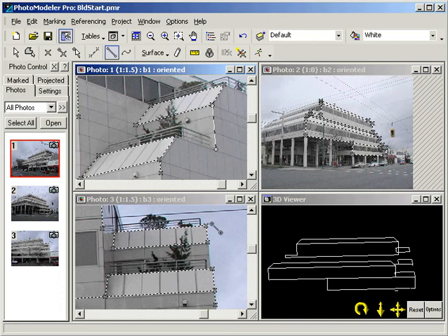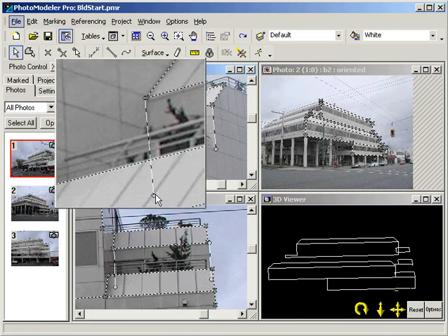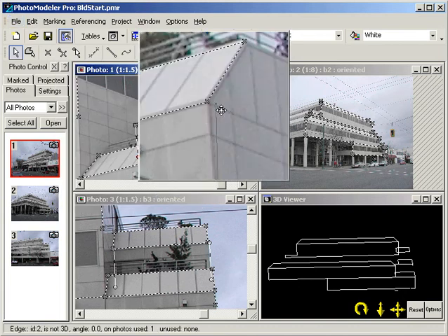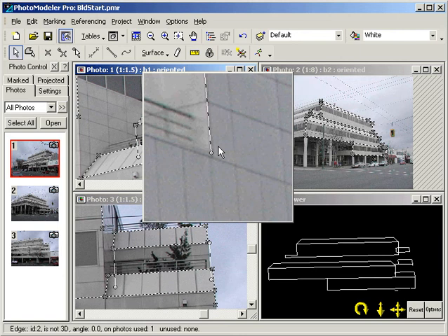We mark the rest of the edges in the patio area of both photos. Again, we can't see the endpoints, so we estimate its end position. The edge's endpoints do not snap to regular 3D points. The position of the edge endpoints must be moved close to the corner so the model will look correct. We mark this point so it closely matches the corner marked by the regular point. We use Alt-Zoom to adjust the edges. Again, the endpoints are not so important as marking the edge line in the correct position.